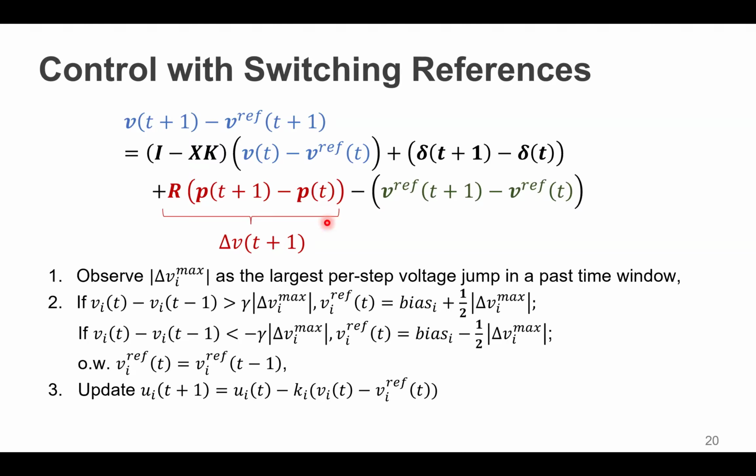It looks like that last second term is more like model predictive because it's t+1. So the red term you are changing in a feed-forward way, because it's t+1 and your feedback is V reference at t or t minus one. I don't know where t minus one got lost. Oh, right, here it's V(t) minus V(t minus 1), so that is the step voltage change, corresponding to this term. There is t+1 minus t, so it feeds forward. You're trying to cancel the predicted increase in P by changing the set point in a predictive way, because it's t+1, right?